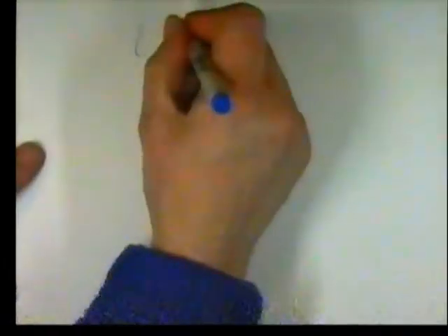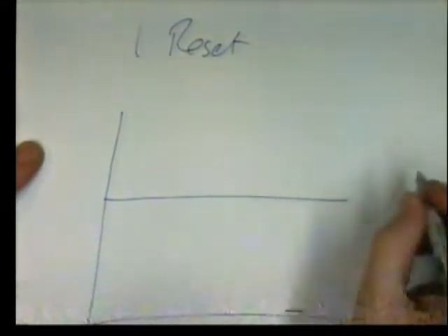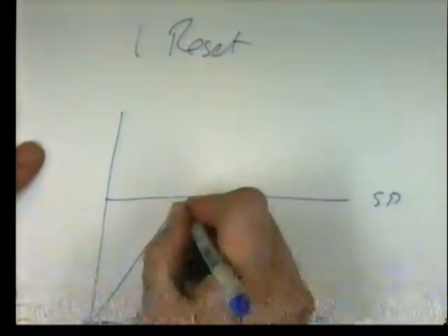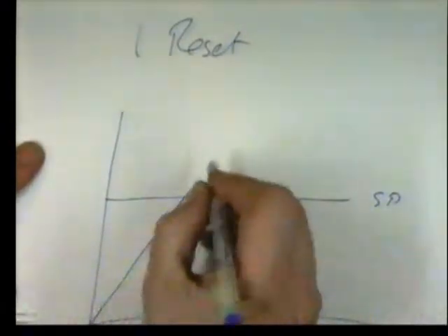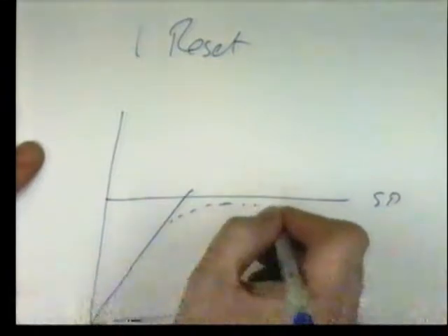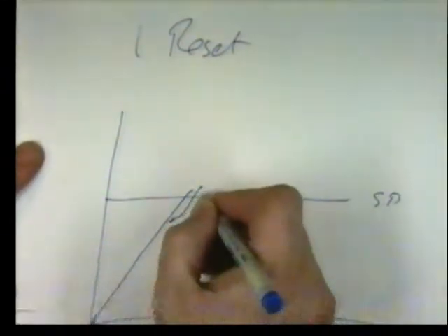The other method, this is a different method, is the integral reset. What the I reset does is that it uses the concept, look, if we're trying to reach our set point and we have gone through it, the I term has done the job. We would have been doing this in our steady state error. The integrator has yanked us up and got us through.